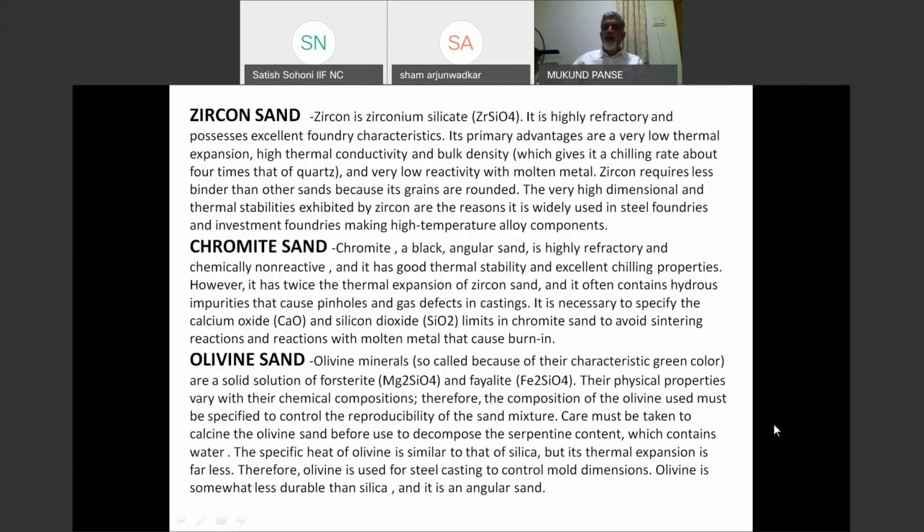The sand grains are round in nature. Unfortunately, the cost is very high. This is a byproduct of heavy metal production, that is atomic energy applications, and hence its application is being steadily discouraged for foundry use. Now it is mainly used only in paints or in some proportion to some very high alloy and intricate investment casting slurries.